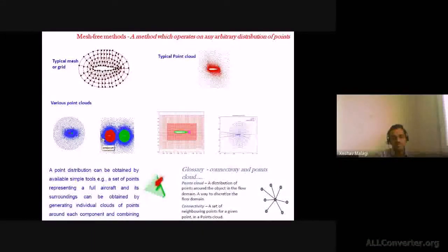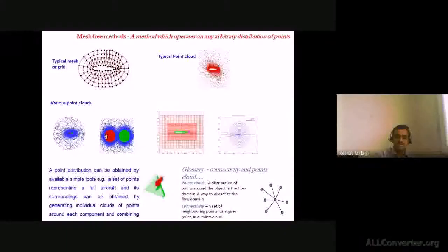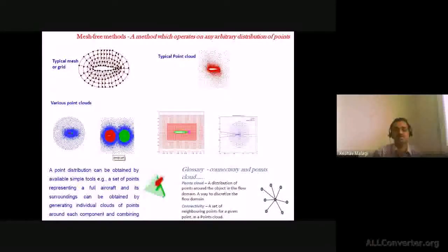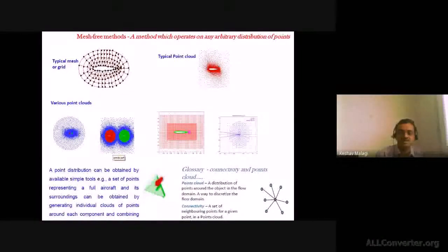But in the mesh-free method, you freely use grid generation, in a very simple manner, without constraining it to satisfy all the properties that are required for a finite volume method. So you use the existing grid generators in a very efficient and easy manner to generate quick grids, without worrying much about the quality of the grid.